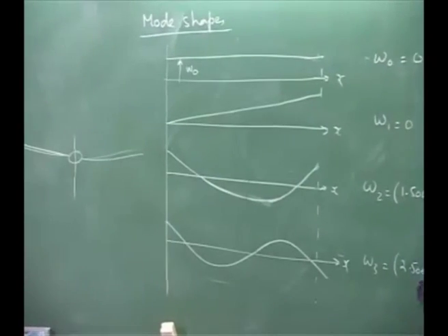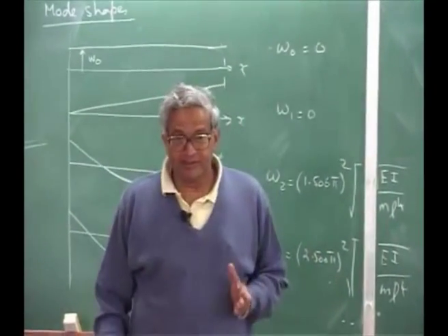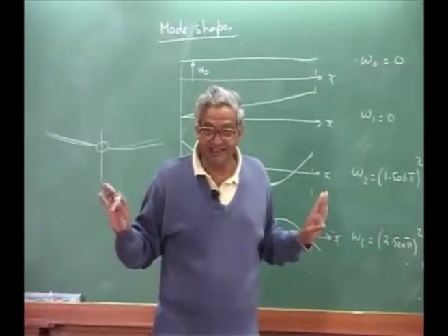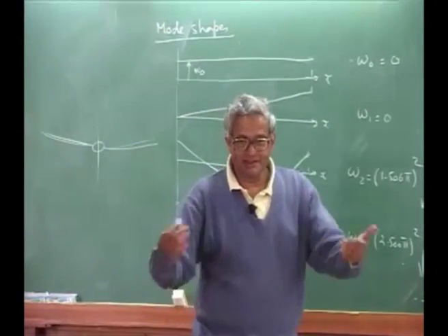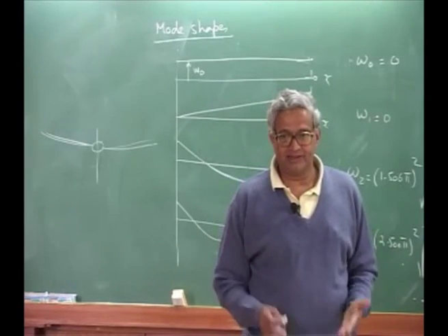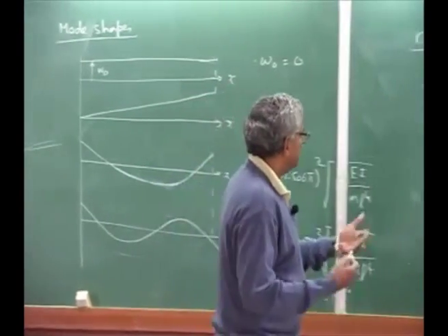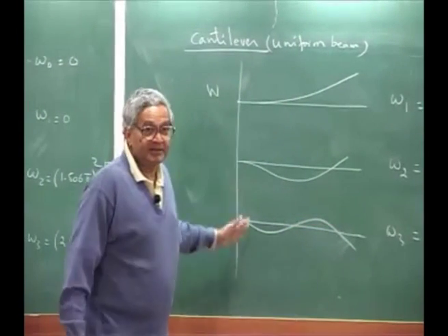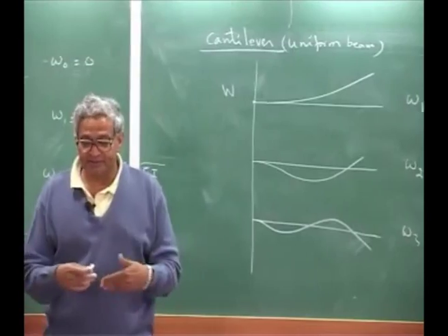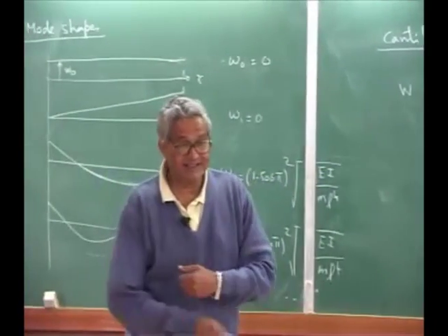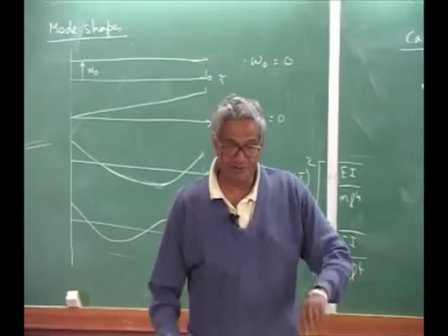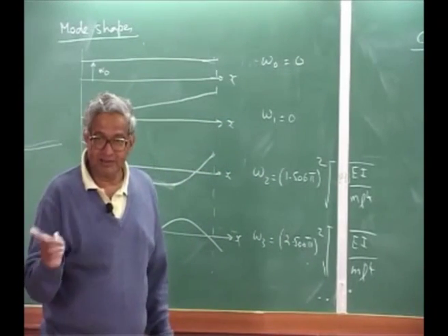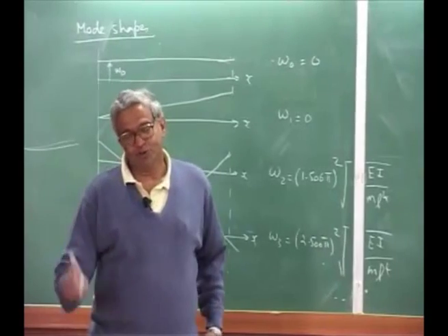So you find for the cantilever beam, the beauty is the equation is not changing. What is changing is only the boundary conditions. Because of the change in boundary condition, you are getting different frequencies, different shape functions, or different eigenfunctions. So that is the essence of this. Your field equation may remain the same, but your boundary conditions will completely change the solution.